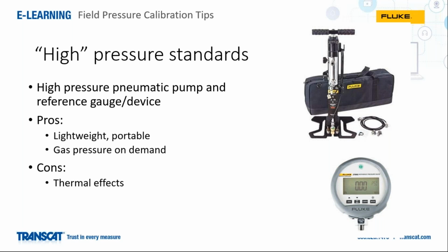The U.S. government, various branches, has put out some guidance in various forms over the years, but generally this goes back to the manufacturer to determine how a device is calibrated. A specific device might take a variety of points, ascending and descending. So typically in our labs at Fluke calibration side, we'd take ascending and descending points to allow us to check hysteresis in instruments. That's not always done, especially if you're dealing with lower accuracy instruments.